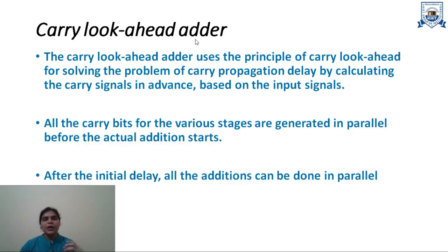So how does a carry-lookahead adder solve this problem? It solves the problem by calculating the carry signal in advance based on the input signal. As soon as these inputs are given to the adder, it starts calculating the carry signals to be generated at each stage. Once it has the carries calculated, it will use all the carry signals in the addition process.